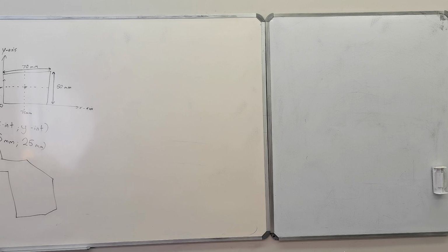For a cube, the center of gravity would be along the x-axis. It will be a over 2. It's basically the same thing, right? For a cylinder, when they're drawing it, the circle center would be found at 0, and its y-axis would be the height over 2. For a cone, the center of your circle will be found at 0, and for its y-axis, it will be height over 4. Just make a note of all that. You'll need to go through it and learn it.